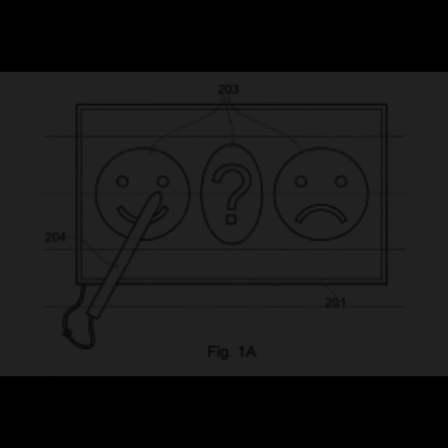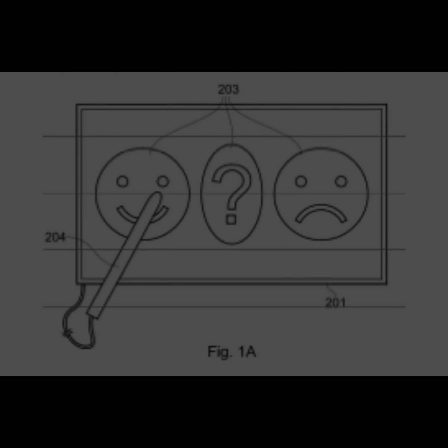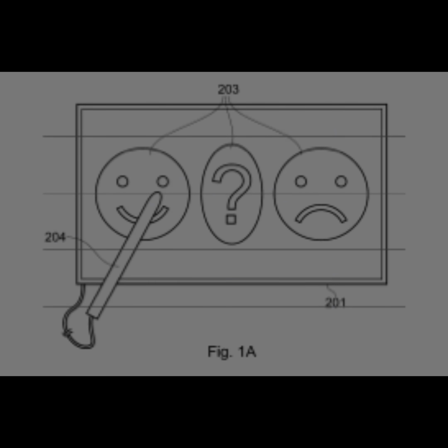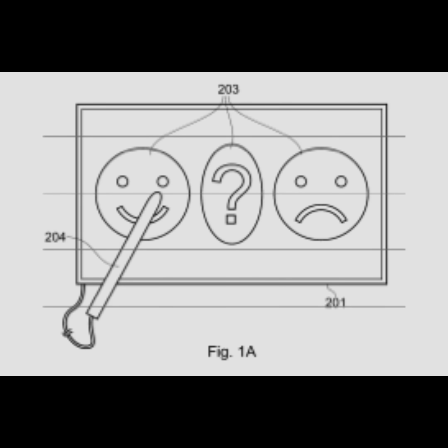The interior surface of the hemispherical support 2 is provided with a resistive layer 6. The resistive layer 6 is preferably coated directly on the support, but it could also be fixed to the support by means of an adhesive layer. The actuator 4 comprises a conductive element 8 at one of its ends. The conductive element 8 is in contact with the resistive layer 6. The conductive element 8 is electrically connected to a control unit 9 via contact areas on the ball 5 and on the socket of the ball joint. The control unit 9 is mounted on the cover 3.